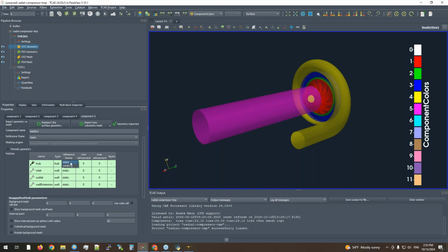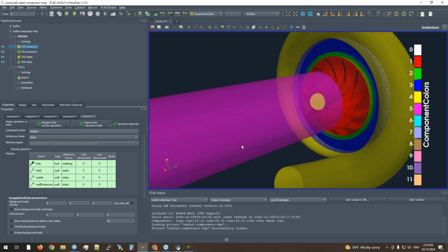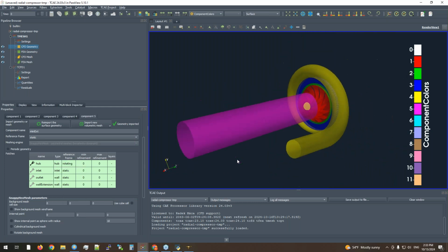For rotationally symmetrical parts, we can also adjust the rotation within the static component. So here we tell that the velocity of the patch will be set with respect to the rotation speed of the rotor. Then inlet, so you need to set the physical inlet into the domain. So this is the inlet.